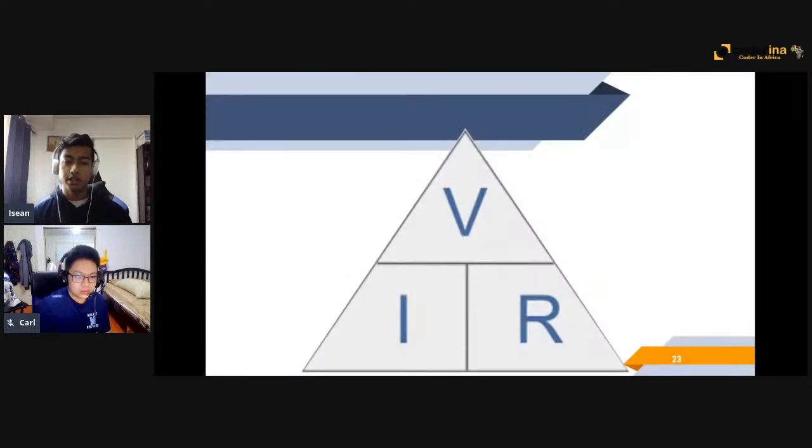Okay, back to this image. Ohm's law talks about a few relationships that can all be summarized in this triangle. We have V, that stands for voltage, I, that stands for current. Again, I don't know why they did that. R, that stands for resistance. Using this triangle, we can find both the relationships between the 3 terms and find an unknown value if we have the values for the other 2.